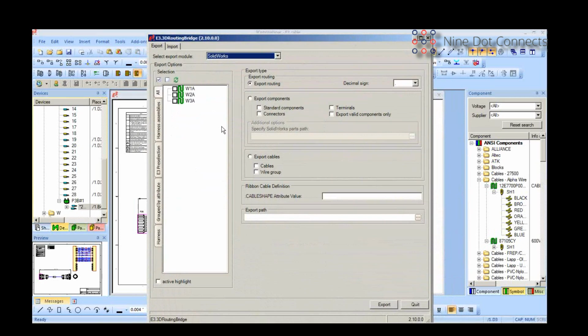Then it looks at the rest of the information and it highlights connections. And these are just rough estimates of the route it would take. So now you can adjust this highlighted line around the model to say, okay, this looks like the best route for me to take. You can adjust or move the merge points if it's a real harness with many connectors hanging off that harness. So you can move those merge points.